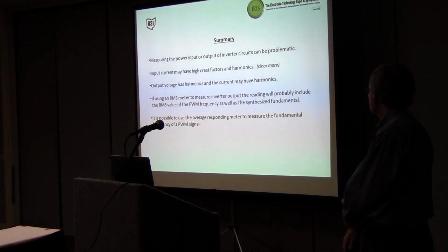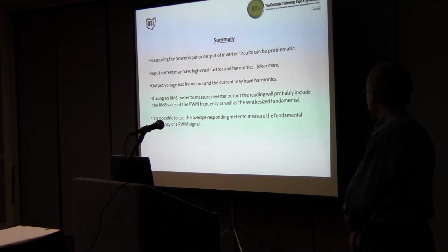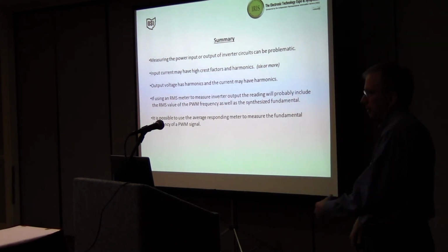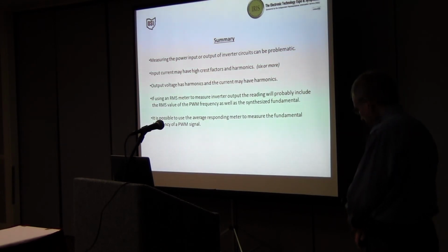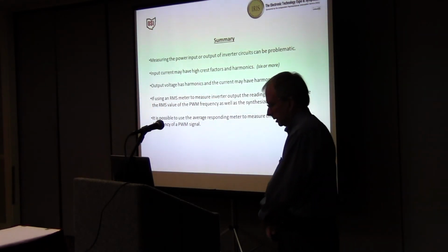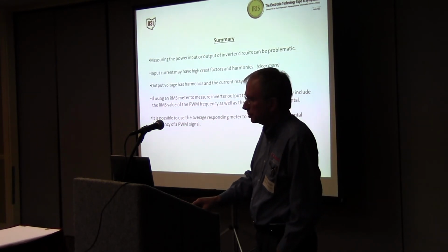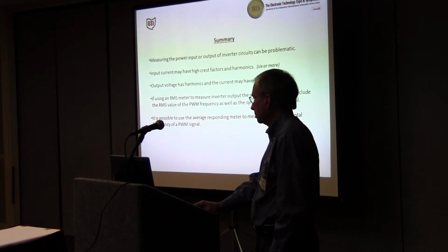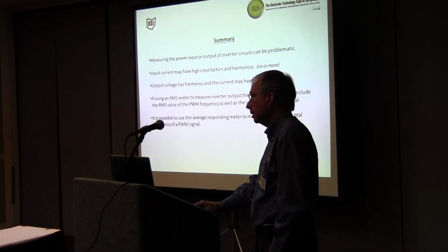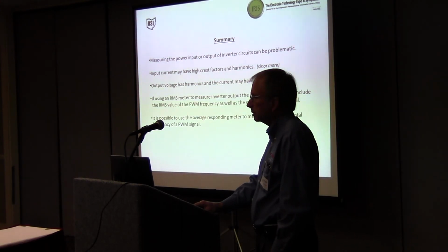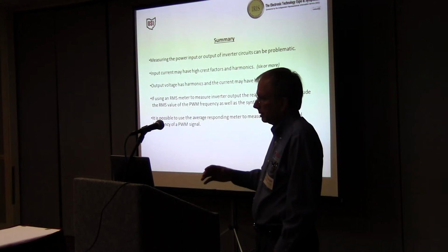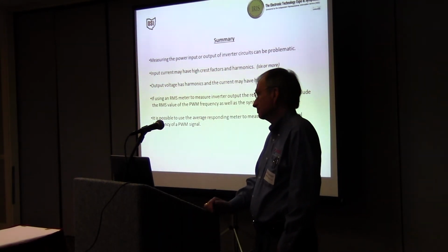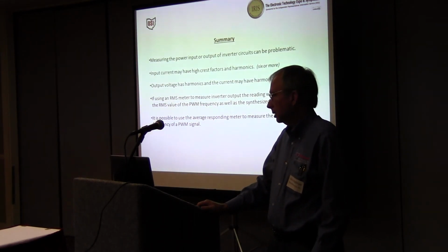Yeah. And again, I pointed out that it's possible to use an averaging responding meter to measure the fundamental. We get into a lot of other interesting situations, and my compressor experience is where a lot of this came from. They no longer just go from 30 hertz to 90 hertz. They basically soft start compressors so that you minimize the inrush. So now they want to make measurements down to 2 hertz. Really? Oh yeah.